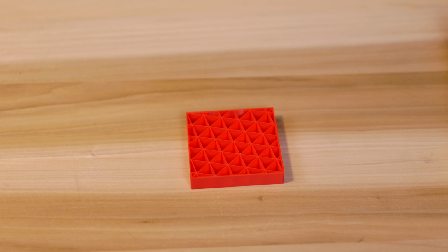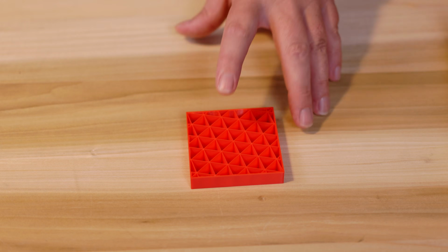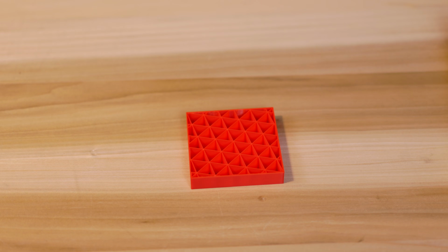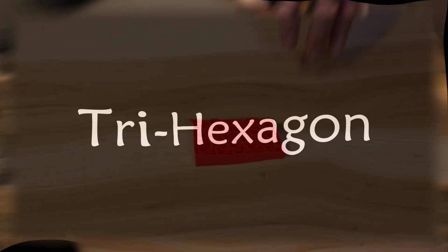The con is it's slower than rectilinear. And the printing tip is this is ideal for mechanical parts under tension. So if your project is mechanical parts that are under tension, then consider using triangles as your infill pattern. This particular cube took 1 hour and 5 minutes to print, and it took 69.94 grams of material.